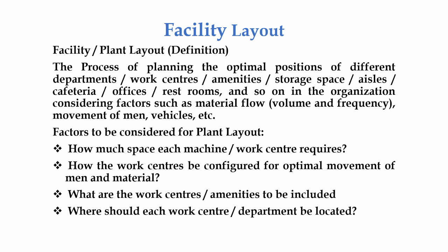and how best we can organize the positions of different departments, work centers, amenities, storage space, aisles, cafeteria, offices, restrooms, etc. within the available space in order to optimize the material flow as well as the movement of men, vehicles, etc. So we can define facility layout as the process of planning the optimal position of different facilities in the organization, considering factors such as material flow, movement of men and vehicles, etc.